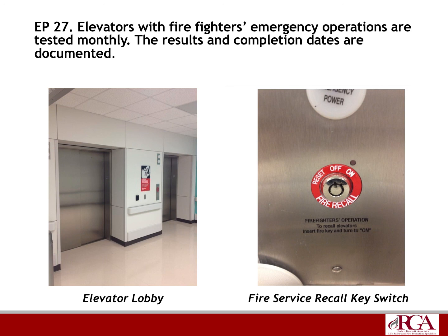Like I said, on an annual basis, they're going to check to make sure that these elevators recall automatically via detection of the smoke detector, and also the machine room smoke detector and the one in the shaft. You have what's called elevator shunt trip. There's a myriad of other safety functions that have to be tested on the fire alarm side, and that test has to be done in conjunction with your elevator vendor. Oftentimes, they have to actually get inside the shaft to test that detector. Otherwise, that detector goes untested.